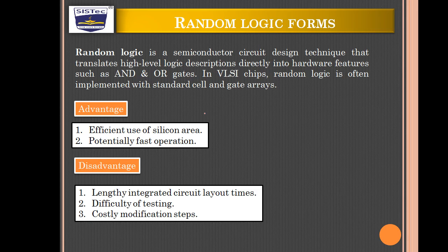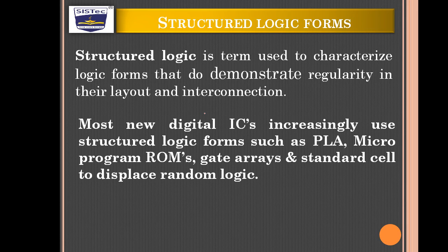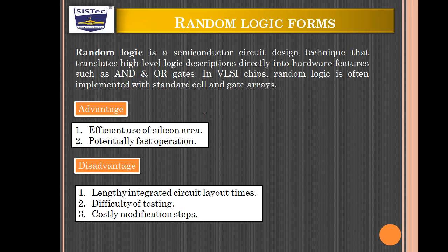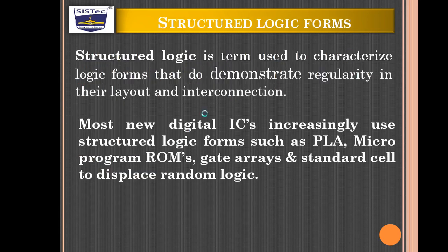If we talk about structural logic form, it is a term used to characterize logic forms that do demonstrate regularity in their layout and interconnection. Random logic doesn't define regularity, or defines regularity only to a certain limit but not properly, while structural logic demonstrates regularity in terms of layout and interconnections.